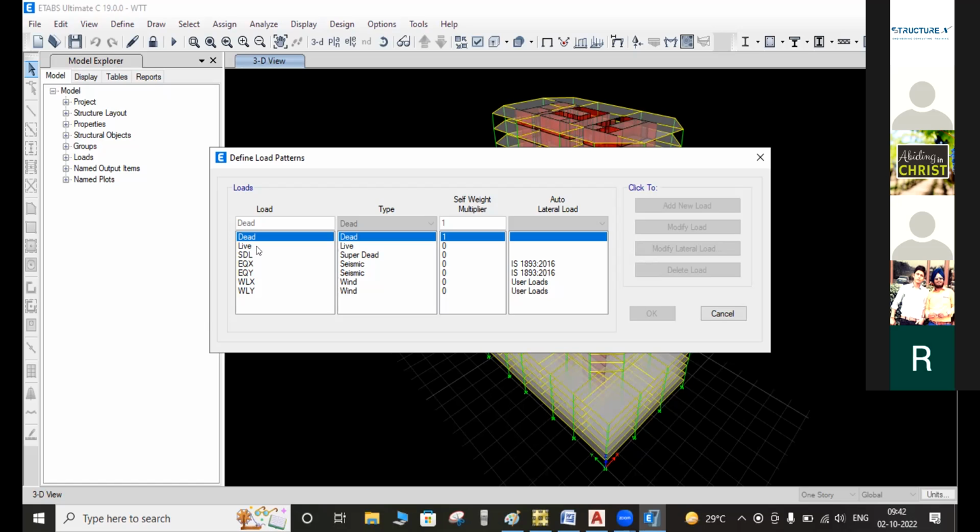Some of the training members here have also seen things with the American standards. But here we are using the IS standard. We can do it with other codes also. For putting the loading, after putting this gravity loading, what will be the next procedure that we have to follow? Sir, the loadings, whether Indian standards or American standards, both are similar, sir. The only difference is the thickness of the material, depending upon the type of material and the density. We are calculating both the same way, sir, but the material thickness will be different.